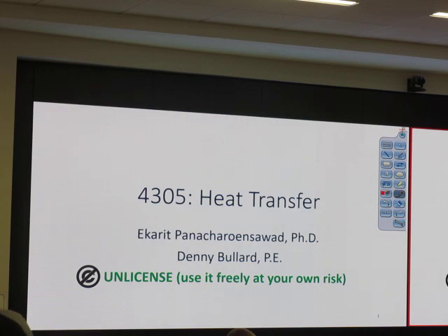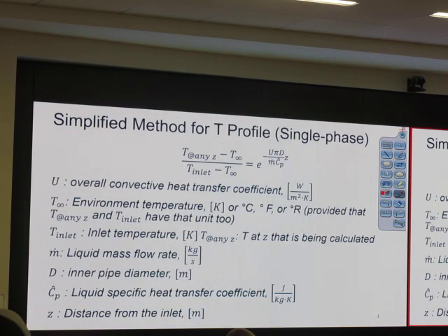On the heat transfer, we talk about the formula for the temperature profile calculation. This formula is for the case of constant fluid property. This means the U value has to be constant. For the U value to be constant, the viscosity has to be constant, and every location has to have the same heat loss.